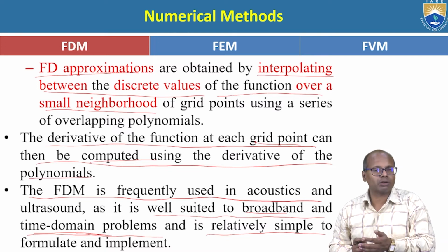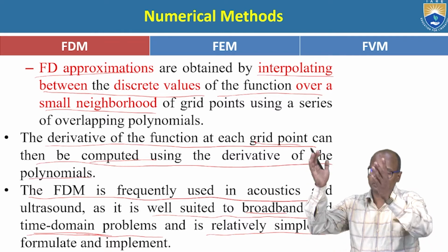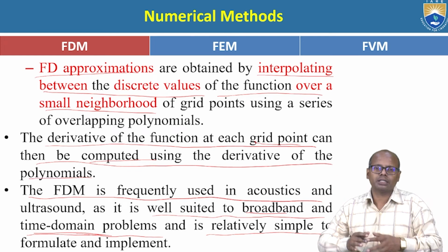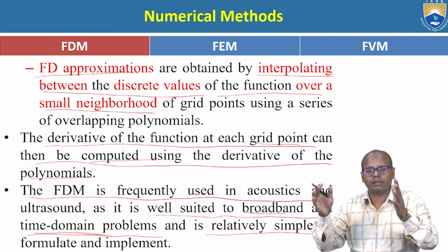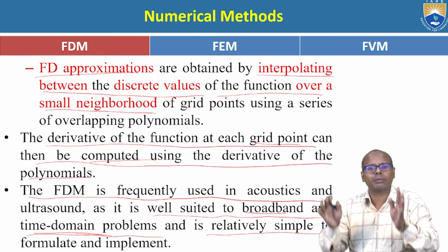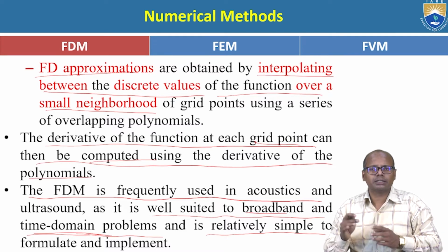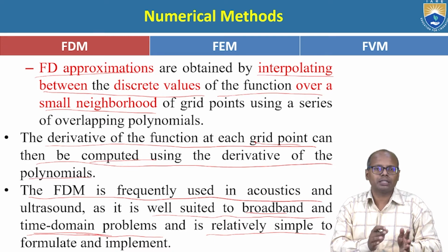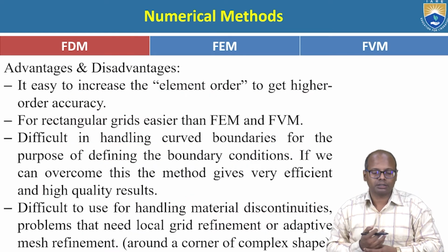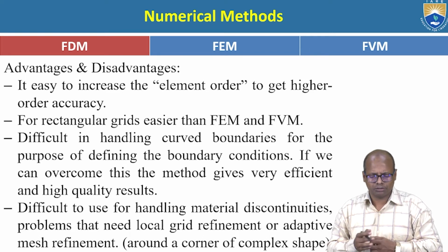See, sound and acoustics are dependent on time. Now in these time-bound problems, since the acoustics are applied in a room, a space, I can easily discretize the domain uniformly. So in such scenarios where the domain can be easily discretized into a uniform structured grid, we can easily apply this FDM. So that is what is said here. And the FDM has some advantages and disadvantages. We'll see here.